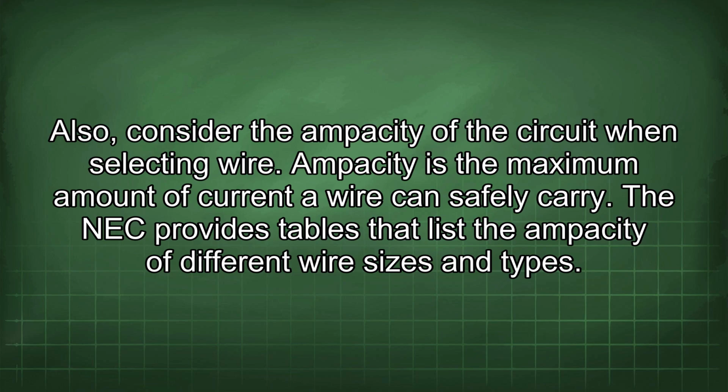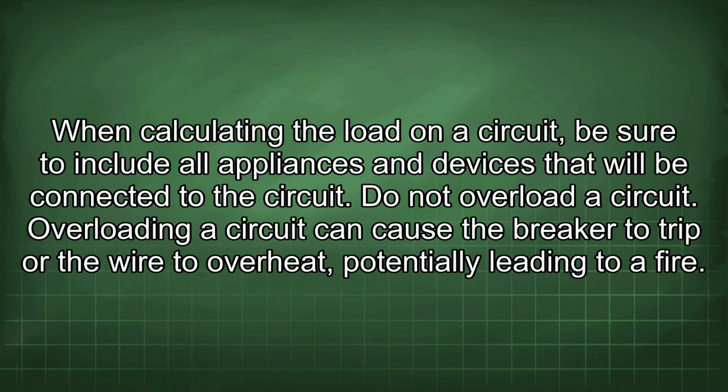Also consider the ampacity of the circuit when selecting wire. Ampacity is the maximum amount of current a wire can safely carry. The NEC provides tables that list the ampacity of different wire sizes and types. When calculating the load on a circuit, be sure to include all appliances and devices that will be connected to the circuit.